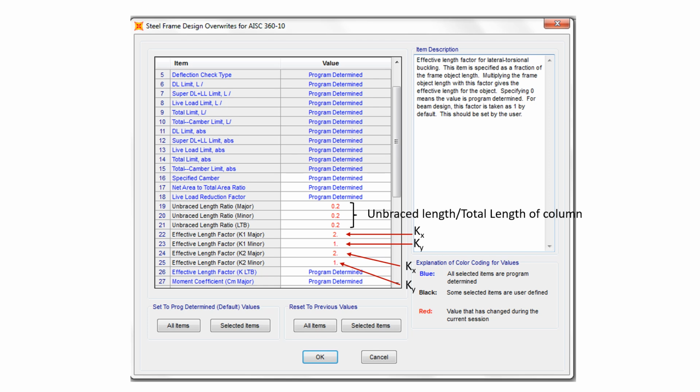If you are using, let's say, a wall across the whole length of the column, in this case, we might, in some situations, consider that the wall will prevent the column from having any unbraced length, so put a very small value. And then you know how to calculate the Kx and Ky using what we learned in chapter 5 for compression members. So it's exactly the same. So you put the values as you can see in front of you.